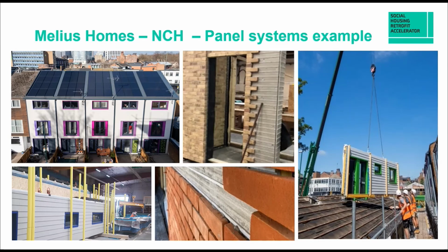The Melius Homes team have been using the Energiesprong approach since 2015 and built the first Energiesprong projects in the UK. At least 60 Energiesprong retrofits have been completed using off-site manufacture, and around 90 homes are in progress using panels manufactured in their Nottingham facility. These particular panels are timber frames being hung from solid brick archetypes. Therefore, they are non-structural or category 5. However, Melius can also manufacture structural panels, which would be category 2.